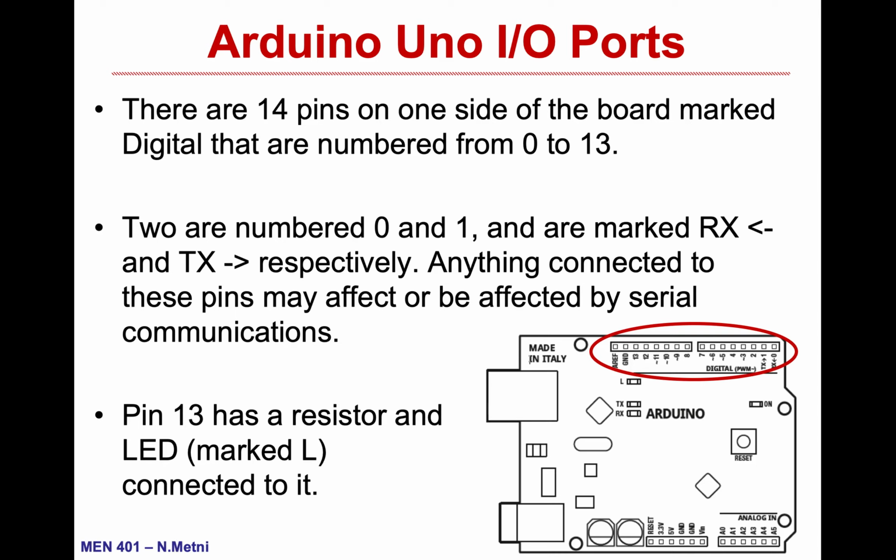Just pay attention that pin 0 and 1 are also used for serial communication. So if you are using any serial communication with any other device, do not use 0 and 1 for normal digital input-output behavior. And I have something else: pin 13 is internally connected to an LED on the Arduino platform.